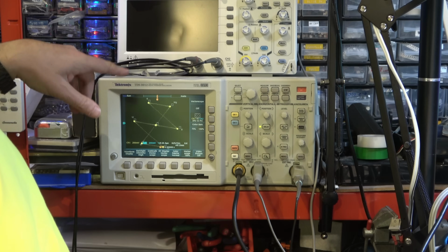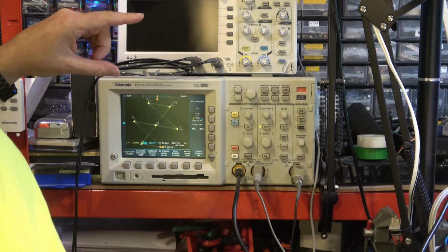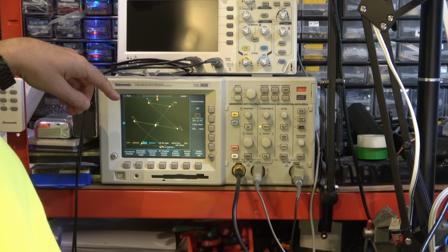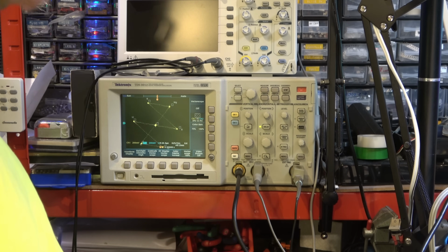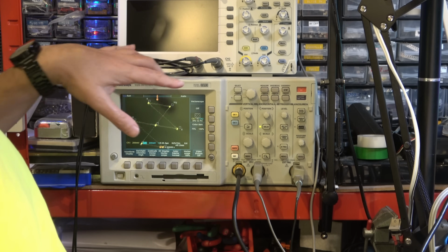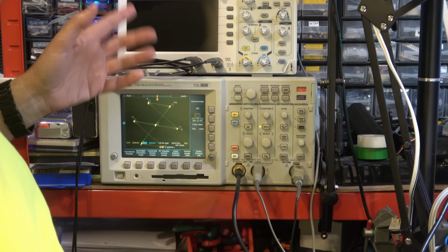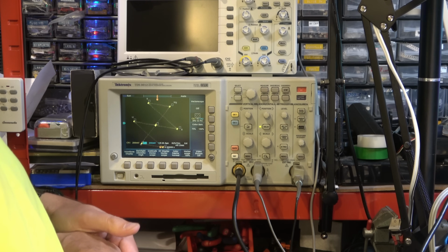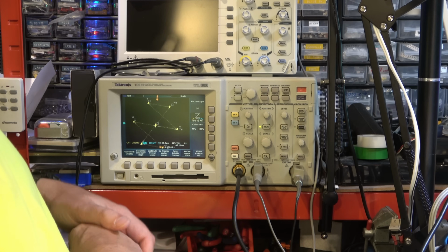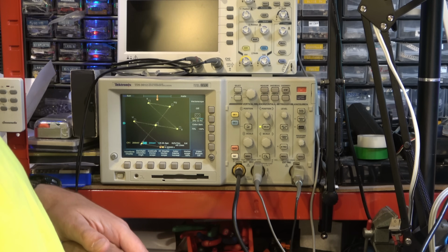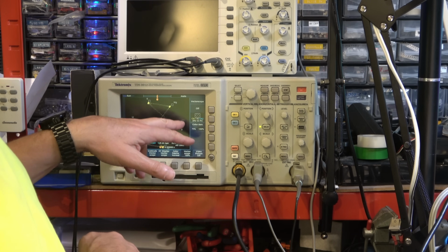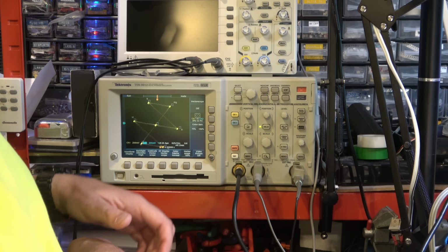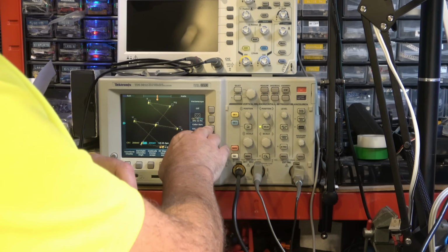By connecting to the correct signals, PB and PR, I think I have a vectorscope display, but it's quite noisy and everything slips down, which may be a genuine case of a problem with the color bar generation here, or could be that something's not quite set up here, but we're not really landing on the dots quite as we should, and there's lots of jitter, so I don't have things quite set up.